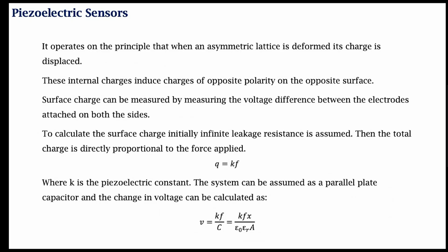Note that we can actually model piezoelectric sensors as a charge source, and that is what it is, is it not? So when I apply a load, it generates a charge. So that means I can model the piezoelectric sensor itself as a charge source that is in parallel with some internal capacitor with some capacitance C. So this is the model of the piezoelectric sensor.